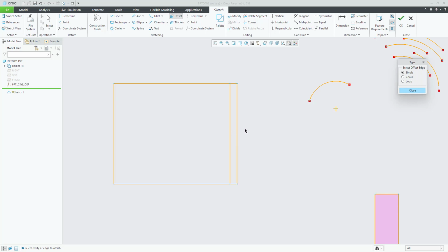So now what if we want this line in this direction? Just click on this line and give the same distance in the negative direction. Give the negative distance and press enter, and you will see the offset is now on this side. Now I'm going to clear it out. Just select and delete. So now what if we want to offset 2 or more lines in this rectangle? So select the offset command, and when we select this single line, we cannot select another line. It is just asking for the distance. So I'm gonna cancel it.